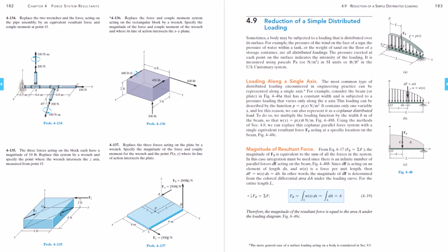And it's called a body force because of the way we model body forces, the way we represent them. If you throw something in the air, then every single atom in that object you threw has the same gravitational force acting in the same direction on it. The entire body has that same force vector. And so you can represent all of those forces with a single force acting at the center of mass of the body. That's why it's called a body force.